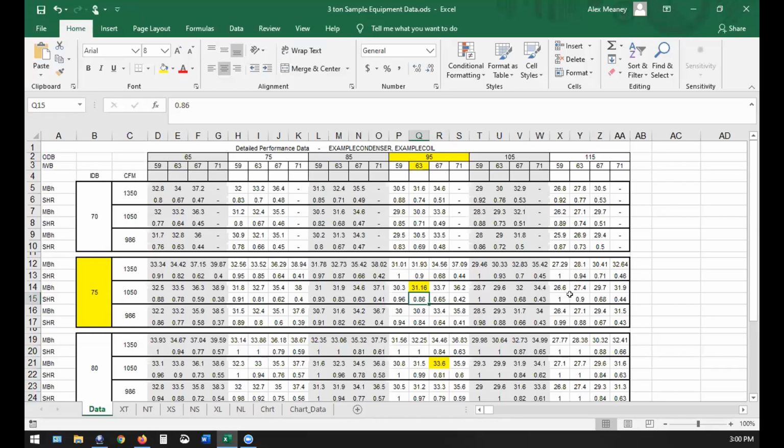And so if you have a house that has 12 air changes per hour at 50 pascals, this system is never going to work in your house. I don't care what the load is, I do care what the load is. I care what the latent load is. And there is no way, unless you're building a house in a desert, that this system would work. And so knowing the load does not tell you what equipment you need. Knowing the load tells you how much heat the building gains, how much heat the building loses, and how much moisture the building gains. And it's your job to find the equipment that will do that.